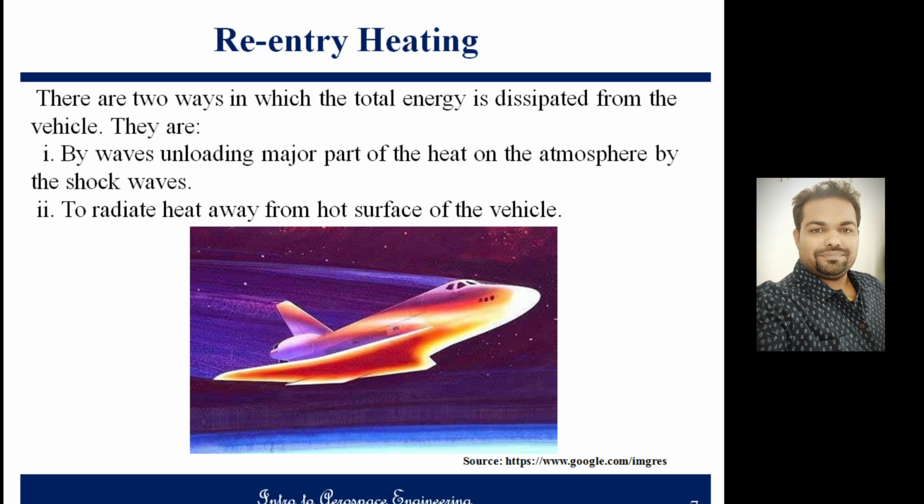So the diversion of heat by a strong shock wave is the result of molecular interaction in the gas around the vehicle. When molecules strike the forward surface, they bounce back. Many of the rebounding particles collide with the oncoming molecules, diverting them from the surface and preventing them from hitting it by direct impact. A blunt nose produces a strong shock wave. Since the fraction of the total heat load that is transferred is directly proportional to the strength of the shock wave,